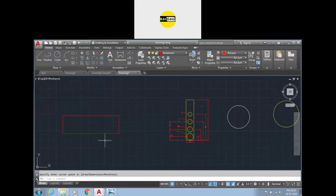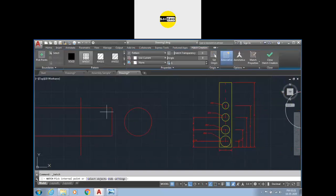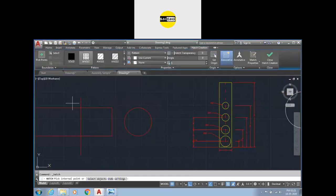Suppose I have a cylindrical shape like this. I want to specify its section from this point. So what will be its section? Its section will be something like this type, and now you have to specify the hatch here to show that it has some material. So go to hatch, it's from H or from here.